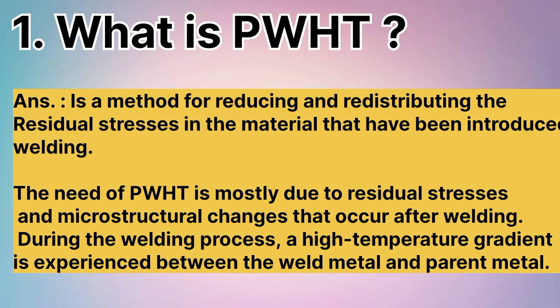Table UCS 56-1 gives alternative heat treatment requirements for carbon and low alloy steel before applying the detailed requirements and exceptions. Satisfactory weld procedure qualification of the procedure to be used shall be performed in accordance with all the essential variables of ASME Section 9, including conditions of post-weld heat treatment.